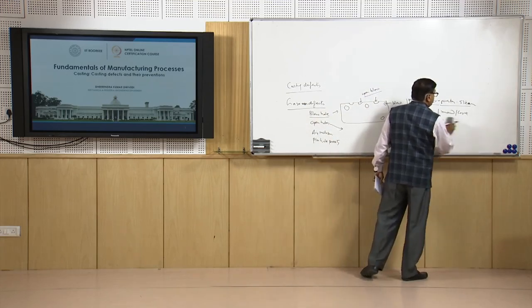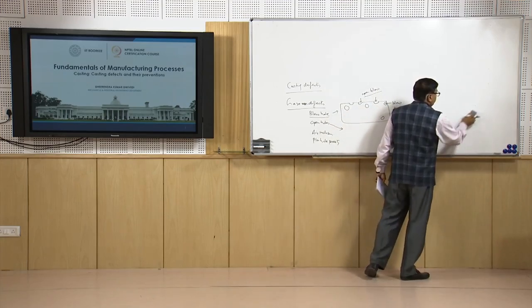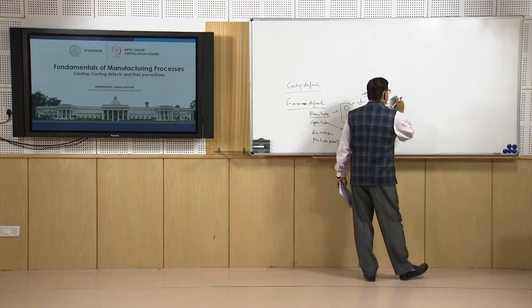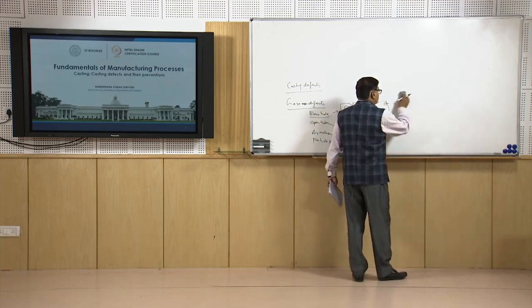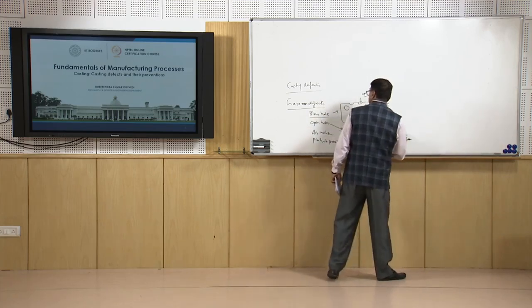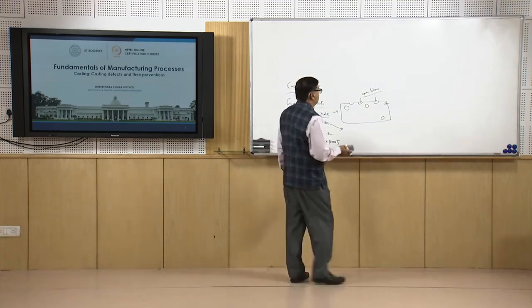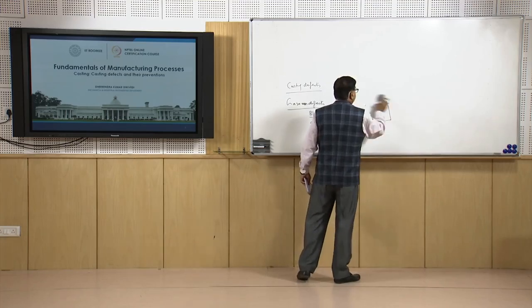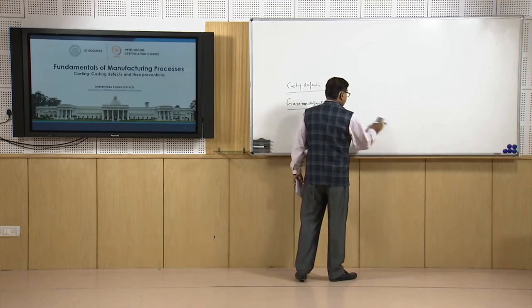So, we need to work on proper venting, improving the permeability and improving the gating system, so that the excessive amount of steam being generated can be taken care of. At the same time, moisture also needs to be controlled properly, so that unnecessary extra steam is not generated.